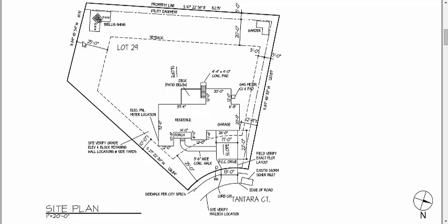Now, so 25-foot setback in the back. What's our side setback? Sides being this side and that side. Well, if you look closely here, you see it's less than 25. It's only 10 feet. So this corner of the house right here is only 10 feet drawn perpendicular to the lot line, 10 feet off of that lot line.